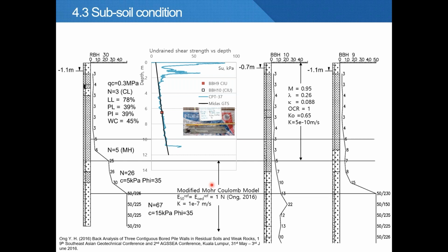It is very important to compare the undrained shear strength of your model with the measured undrained shear strength when you use the Cam-Clay model, such as shown in this figure. We compare the undrained shear strength from the Cam-Clay model with the undrained shear strength from the CRU test as well as the CPT test, so that you know what undrained shear strength you are modeling when you use the Cam-Clay model, because you don't input undrained shear strength in the Cam-Clay model.